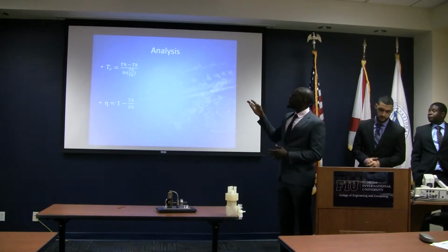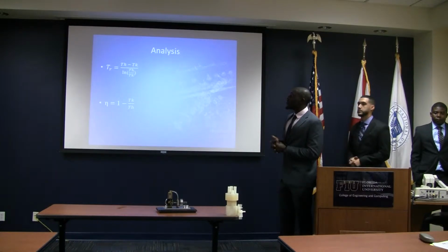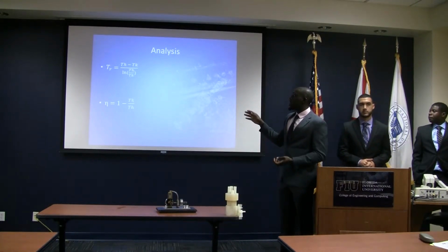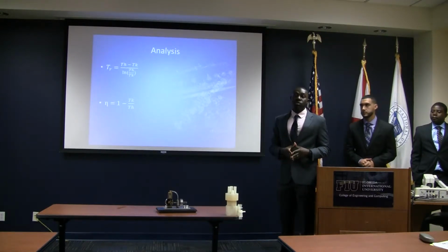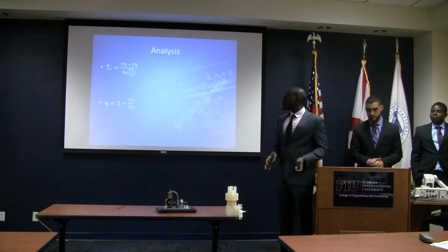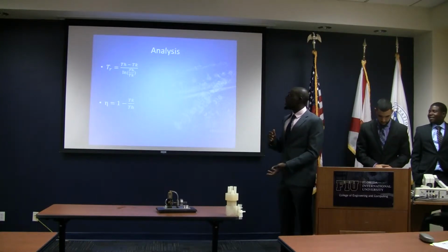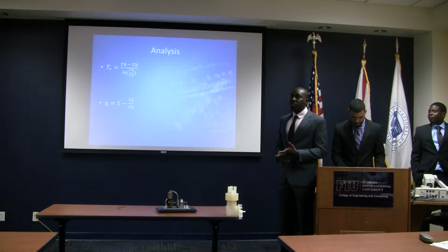That was why the regenerator was very important to us, and we have to talk about it to let you know how important it is to a Stirling engine. Not all Stirling engines come with regenerators, but if you do have a regenerator in your Stirling engine, it's much more efficient and it generates more power as well, because it makes it faster and cooler at the same time because of the temperature difference it gives.